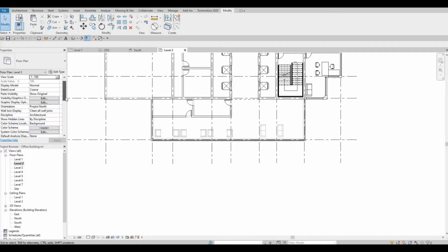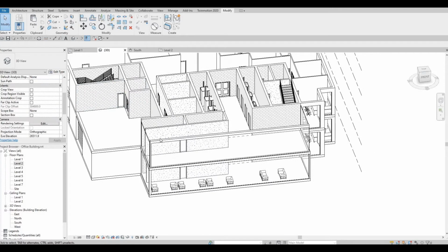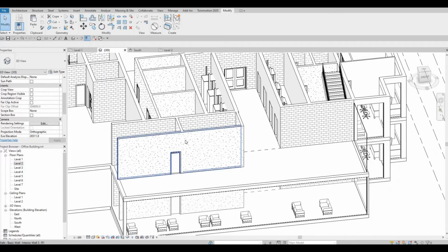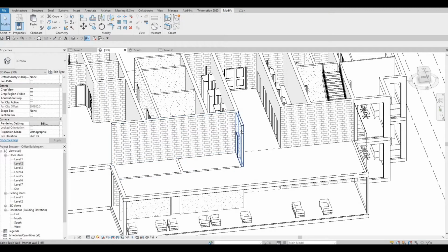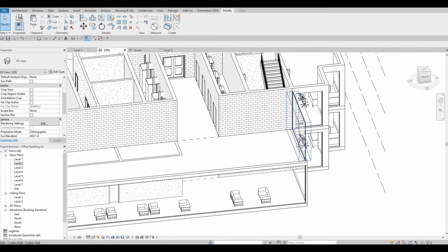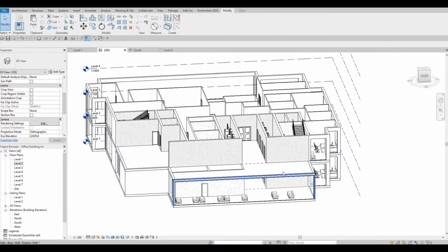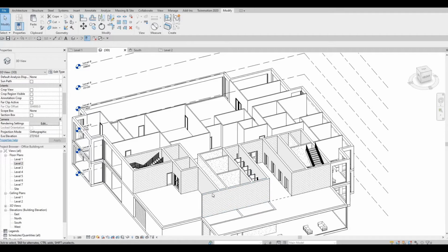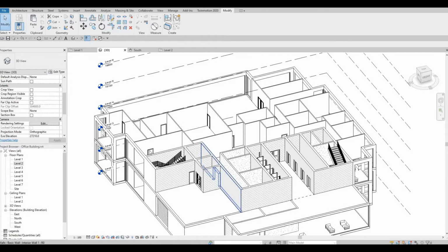and our underlay is on. So we just need to go to under properties and go to underlay and choose range base level to be none, so that we don't need to see what's going on below. We could just delete it from here. So it's up to you where you want to delete it, but I just want to delete it there. So I'm deleting it there. And then maybe we could trim this one here.